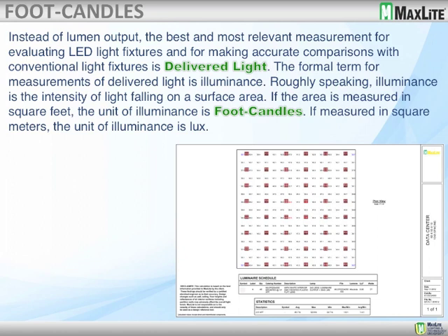And this is the true way to compare the old non-LED light source fixtures to the new LED light source fixtures, and that is to have a lighting layout done. And we can do apples to apples in the form of foot candles or in some cases lux.